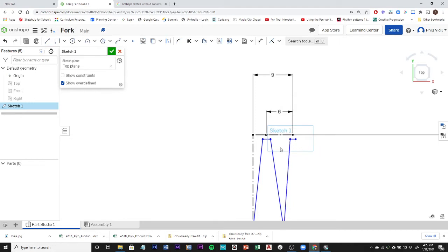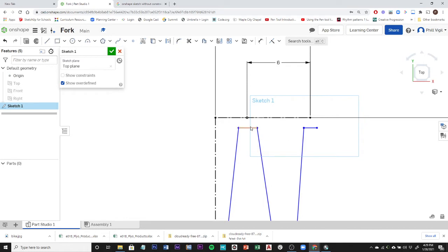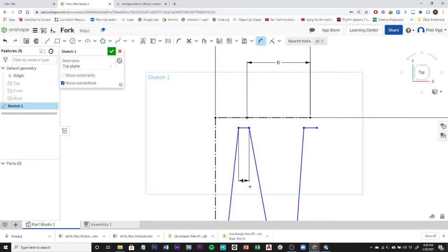And now we're going to add some dimensions. So this point I want to be about 1 millimeter. So it's pretty small, but it's not an exact point. So I'm going to click here and dimension this. And then change it to 1, or 1 millimeter. And I want these two to be equal. So I'm going to use a constraint that makes these two equal. So now this one has been shortened to 1 millimeter.